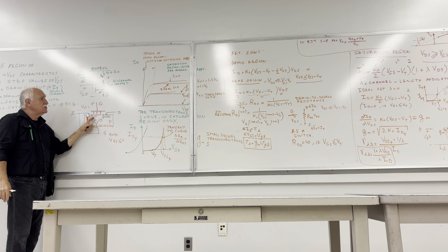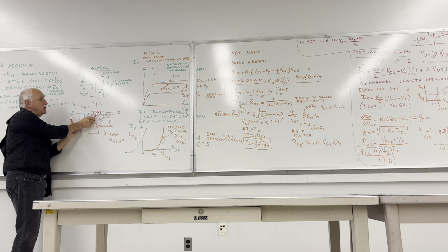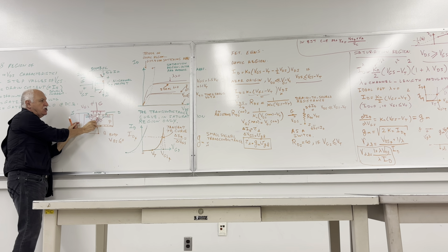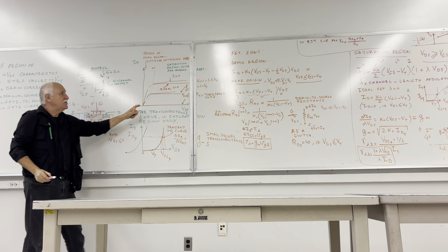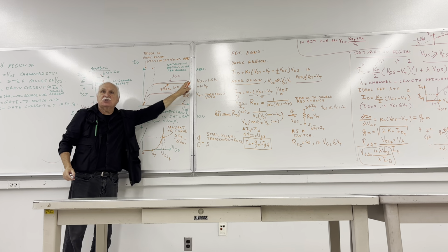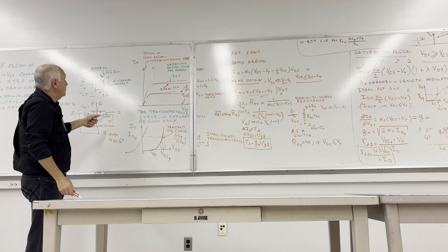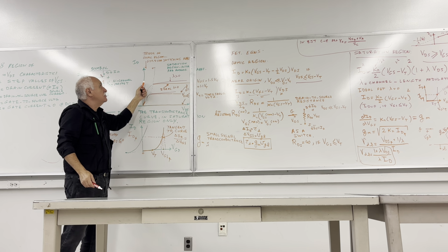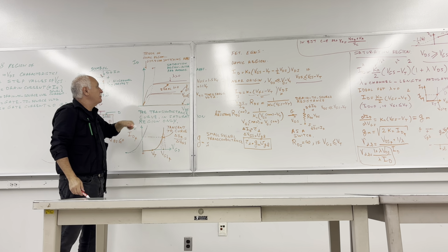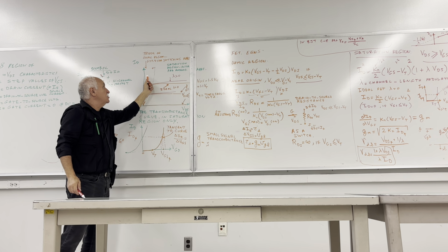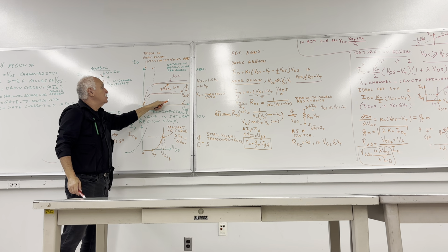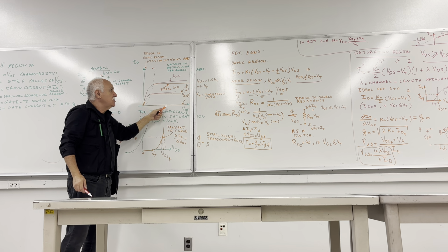And as a result, the drain to source voltage affects the actual value of that, the modulation of that channel, because channel gets shorter or a little longer with the drain to source voltage. That's why we get this slope. So I gave you the characteristic ID against the VDS, and I said drain current is controlled by the gate to source voltage.